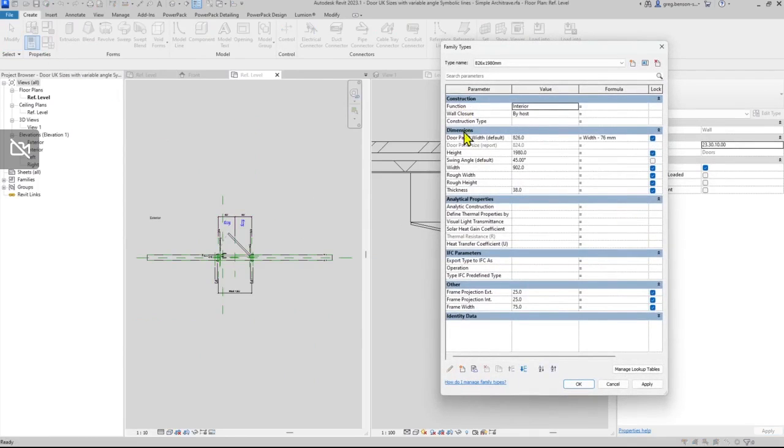Every time you add a new parameter, test it straight away, one at a time. Don't add a parameter and add another one and add another one and then test it, and then find that something breaks. Otherwise you won't know which parameter is not working correctly. I cannot overemphasize this. We need to flex our model, flex our Revit muscles. Every time you add something new, test it straight away.